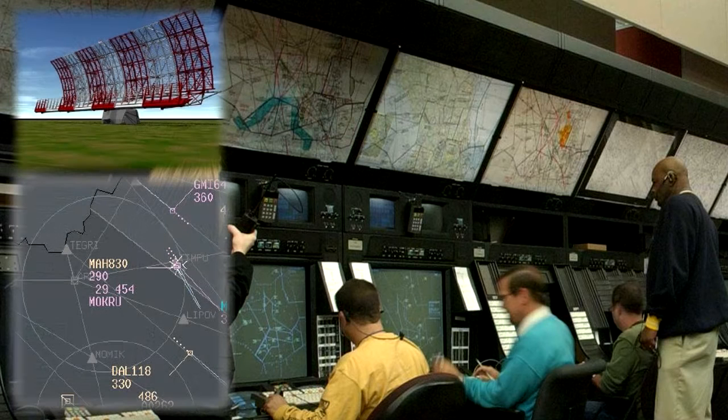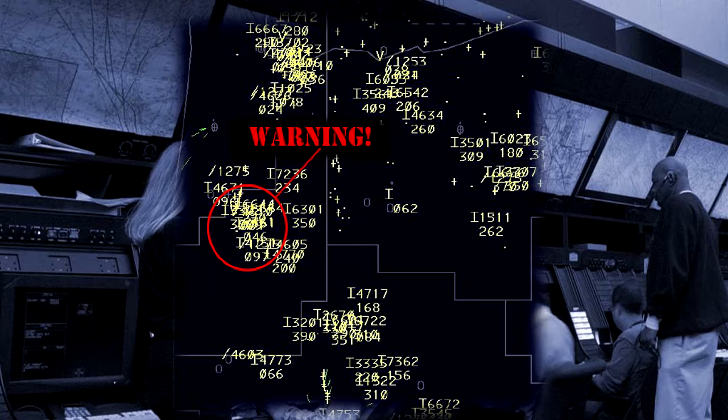Because air traffic control is responsible for separation of traffic operating under instrument flight rules, any air traffic control radar system must have a high degree of reliability, availability, and integrity. It almost goes without saying that because the system is so heavily relied upon, it must be backed up. Radar systems should not only display the position of an aircraft spatially, but also provide for the display of safety-related alerts and warnings, including confliction alert and prediction, minimum safe altitude warnings, and unintentionally duplicated secondary surveillance radar codes.